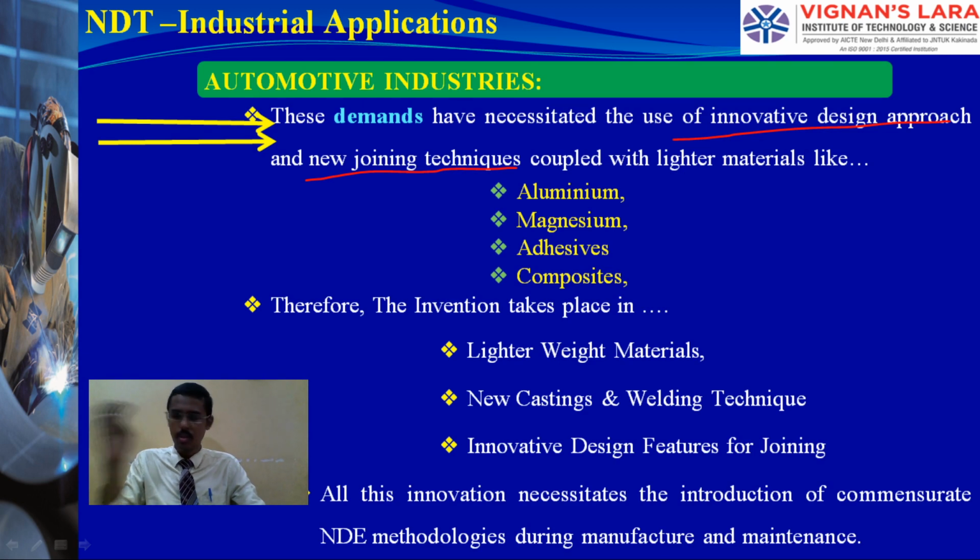Normally we do welding, steel welding, or SMAW, TIG, MIG processes. But new materials like aluminum and magnesium have low melting points. Therefore, we have to develop new welding methods, or new parameters, the current and voltage conditions, and also new filler wires. What material can be added to weld dissimilar materials? All these things are new.